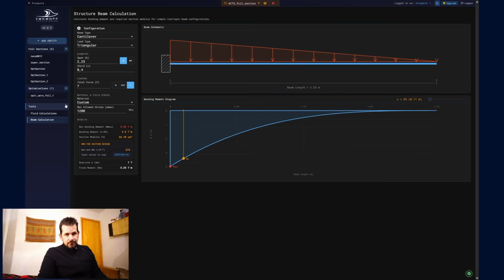So in general, a wing can be considered as a clamped beam sustaining some forces. In this case, the wing of the foil has two sides, so it's calculated on one side, because in the America's Cup the foil had to be completely symmetric. So on one side of the beam we have half a wing, and on the other side the other half, and here we're just looking at half of the wing.